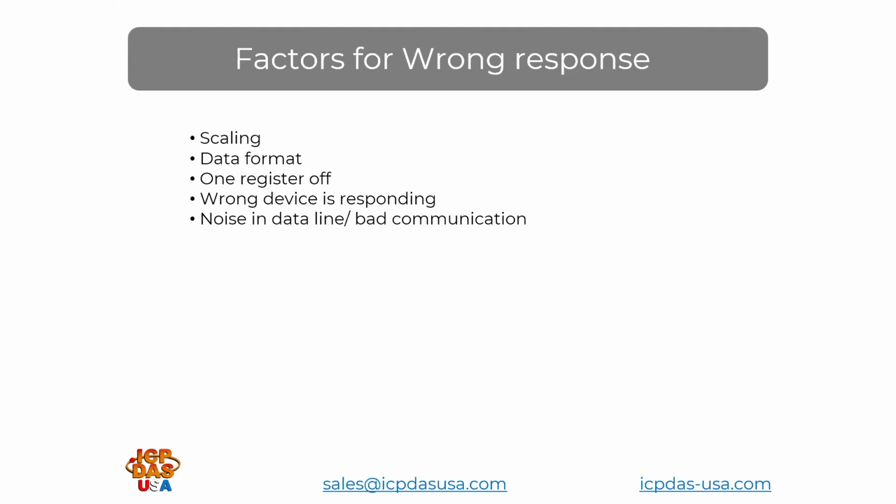Make sure the right device is what you're talking to. Sometimes customers may read the wrong slave device. It's very easy to configure your PLC wrong, where you forget to or don't specify the correct slave device. It would be better if you could specify names within the Modbus table, but of course it's just a number and it can very easily be mislabeled as well.